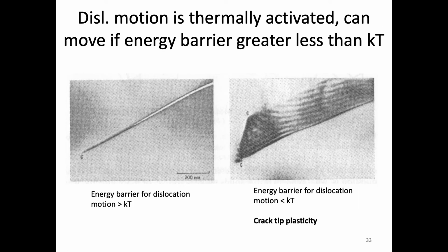All right, so I've mentioned that plastic deformation is fairly rare in that it can modify that expression of K1C if it does happen. But again, keep in mind, in other classes we've talked about how dislocation motion is less common in ceramics because of the ionic or covalent bonding as opposed to metallic.